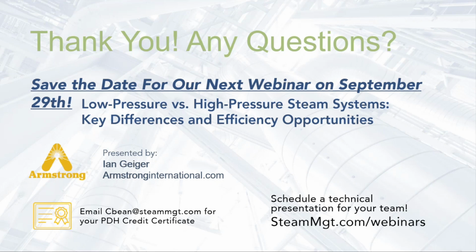Well, first off, that one was a comment under the question, can the SteamEye system monitor all other manufacturers' steam traps or just Armstrong? To answer the main post, yes, it can. It depends on the type of monitor you're utilizing. The conductivity units, unfortunately, are Armstrong specific. However, ultrasonic and temperature units, which are the most commonly used ones, can be used on any type of manufacturer.